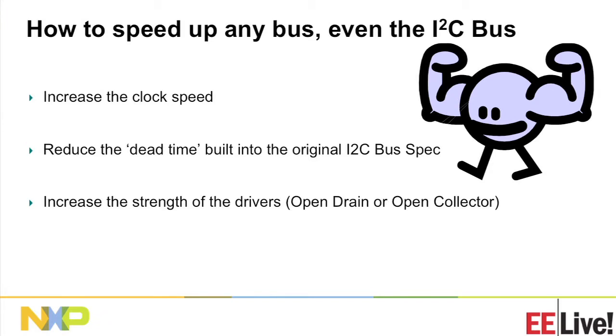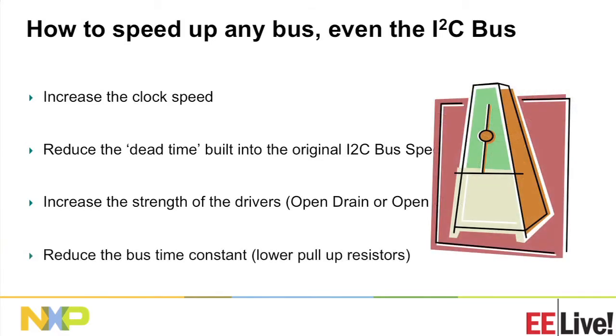Think back to the 1980s technology. We started with 3 milliamp drivers. They were typically bipolar technology, and they were open collector bipolar transistor devices. Using FET technology, we can use a device that has a smaller area on the die and a much stronger drive. So we can increase it from 3 milliamps to currently 20 milliamps. Most of the parts from my employer are better than 20 milliamps, but the spec said you will need a 20 milliamp driver to go faster.